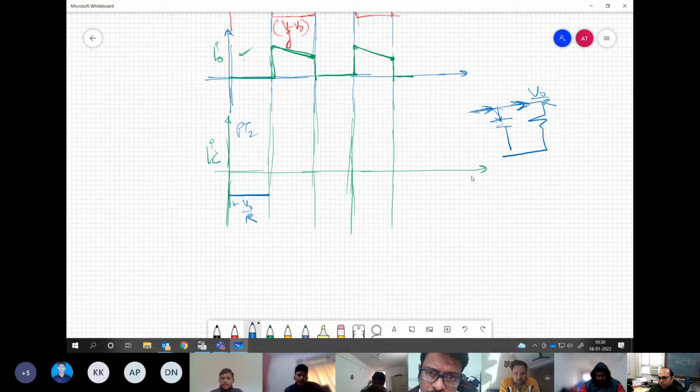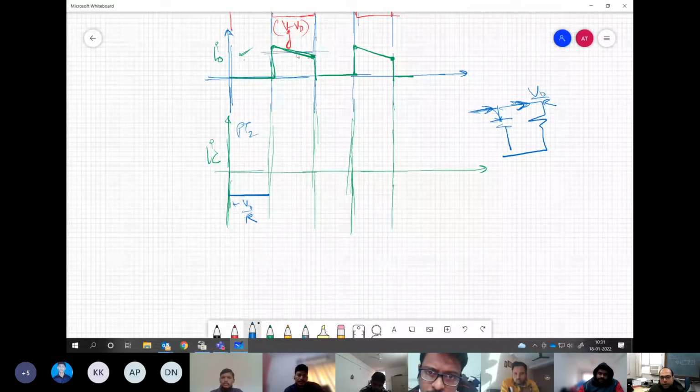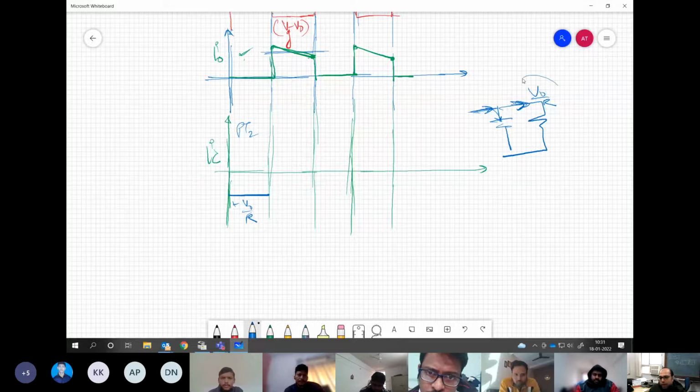You understand the point? So how will that go? Whatever current you have, take the average value of only this part, subtract V naught by R from that, and the remaining will be your capacitor current. You understand my point?